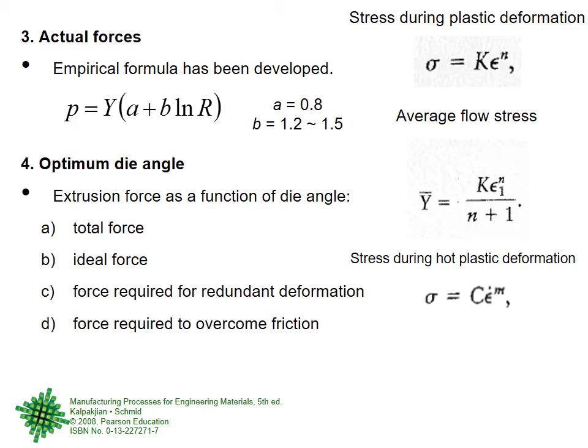If we want to find the extrusion pressure by this empirical formula, the Y and the R are real. This R is the extrusion ratio A naught upon AF. This Y is the flow stress of the material. A and B will be empirical.